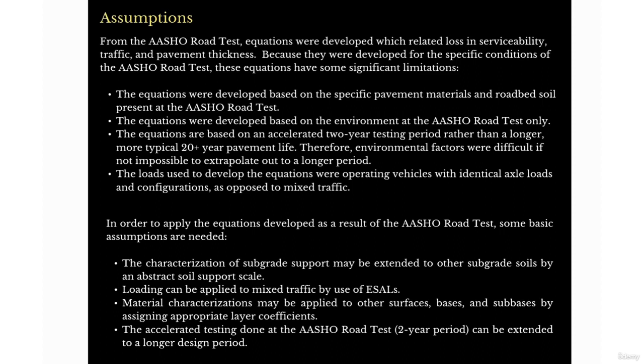Even when you're writing your report, you mention your assumptions, right? So these are the assumptions that you have to be mentioning. The characterization of the subgrade support may be extended to other subgrade soils by an abstract soil support scale. The load can be applied to the mixed traffic load by the ESAL. Material characterization may be applied to other surfaces, bases, and subbases by assigning the appropriate layer coefficients. The accelerated testing done by the AASHTO tests, the two-year period, can be extended to a longer design period. These are the assumptions you are using when you are carrying out the design.